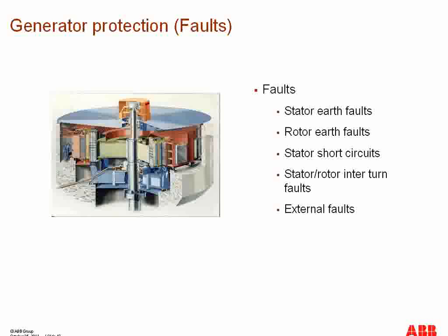We differentiate between faults and abnormal conditions because it's not always necessary to issue the trip command to the generator, because we do not want the generator to be off the power system without any serious trouble. But at the same time, we do not want to damage our generator as well.